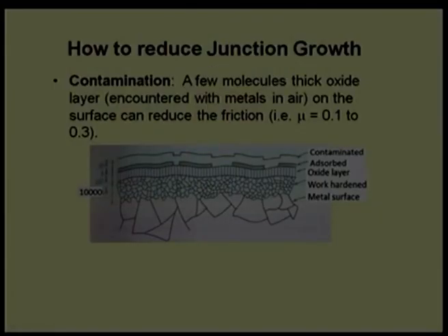We can do this kind of experiment in a laboratory. When the shaft is machined and we immediately try to run it at high speed, we will find a high coefficient of friction and complete welding. However, if we grease it and then run it in the bearing or a subsurface, we will find the coefficient of friction is much lower. The reason is that the lubricant or grease layer coats a thin layer on the shaft surface and reduces interface shear strength. That interface shear strength compared to the bulk shear strength of a steel shaft gives us a good result.